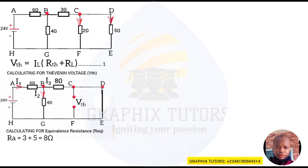Are we there? Now, if you notice, I3 is still the one flowing through the 8 ohm, as a result of 3 plus 5. And I2 is flowing through the 4 ohm. Because different currents flow through the resistors, we say both 8 and 4 are in parallel. I will now use another representation for this resistance. So R sub B is equal to 4 parallel to 8, because 4 and 8 are in parallel due to the two different currents flowing through them.